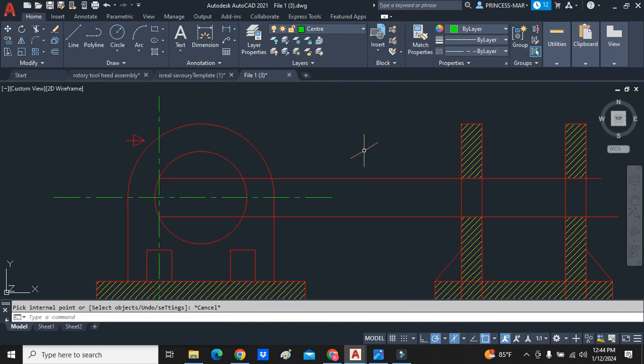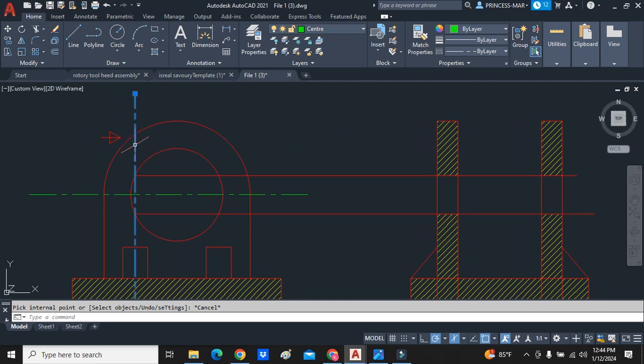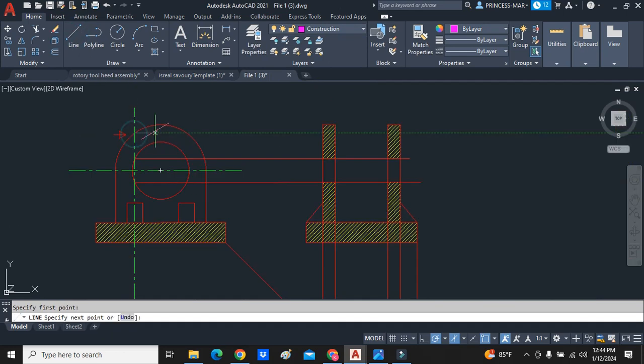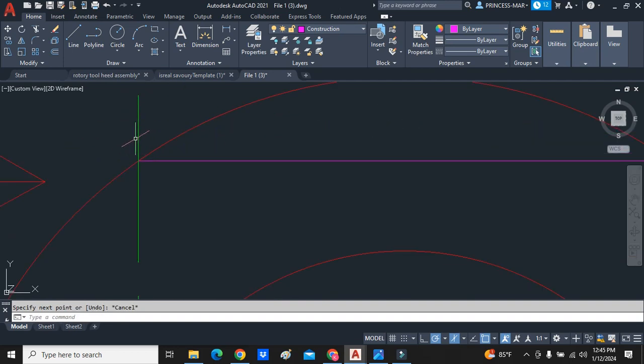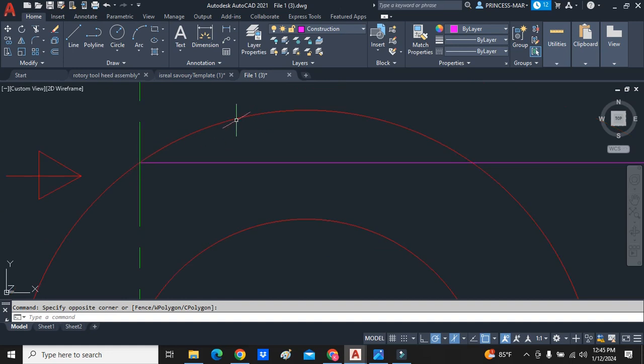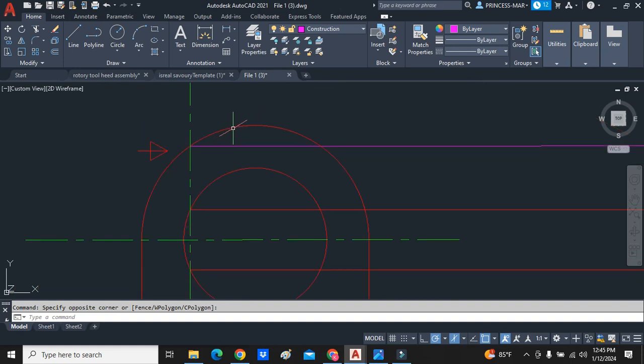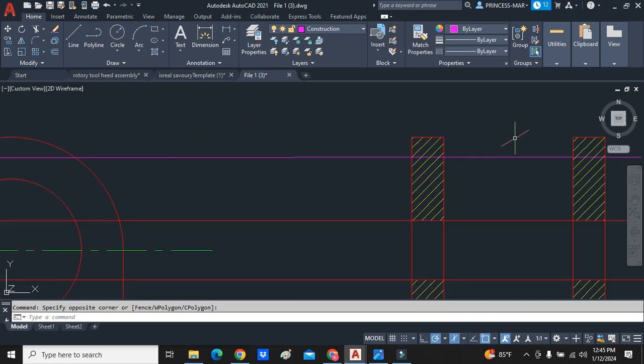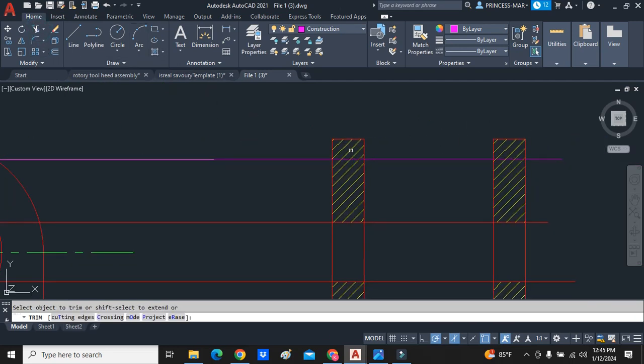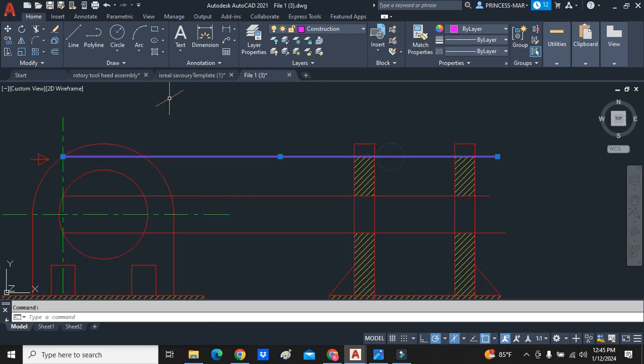The error here that Avron has is that this part is cut straight down here. When Avron extended this point here, it should have been extended across, because this is the point of intersection where the figure is cut. Up here has not been cut, but we can still see this top piece over here. The long and short is, in here should not be section. This top piece does. You follow me with that? Or no?